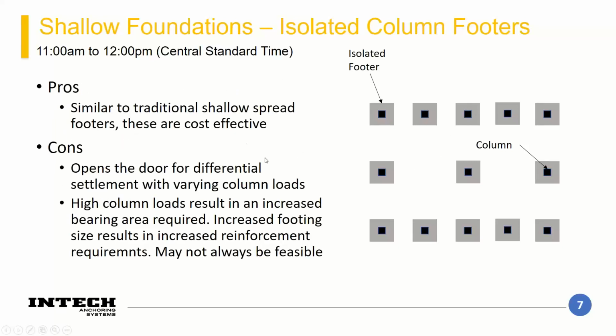So the pros of these, similar to the traditional shallow spread footings, is that they are very cost effective. You're not going to have to do a lot of excavation, and there are lots of documented design aids to help you design for these isolated column footers.